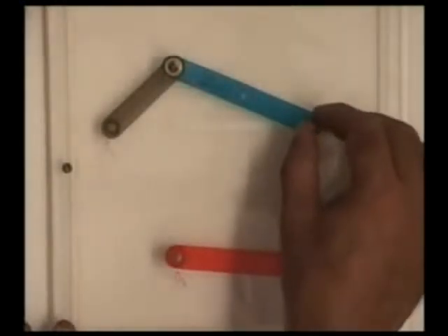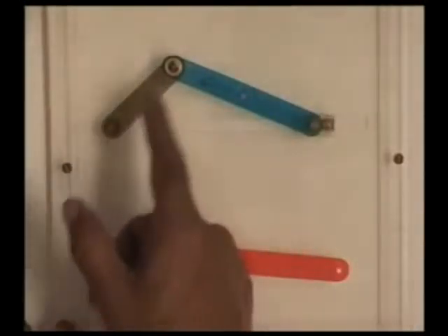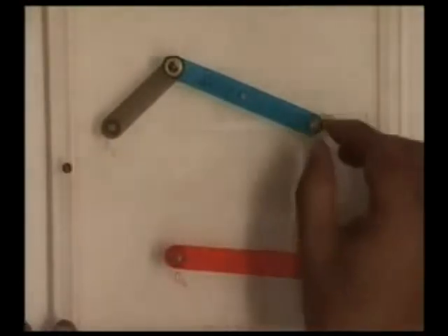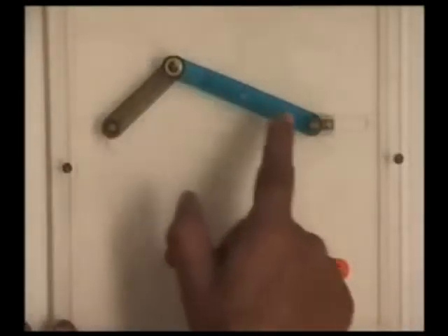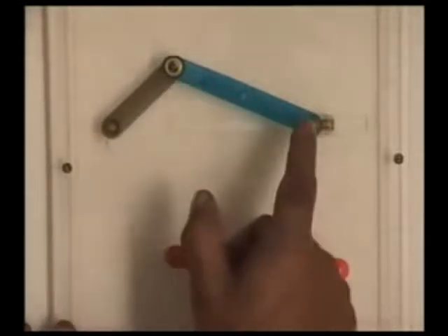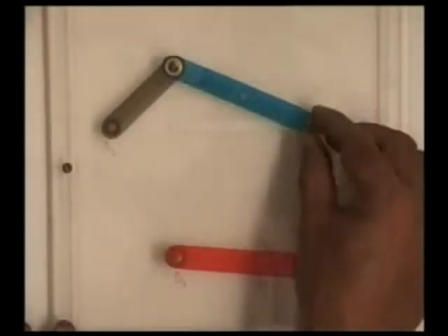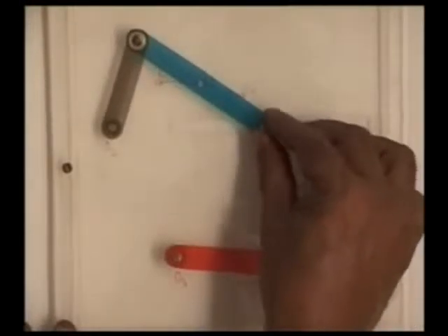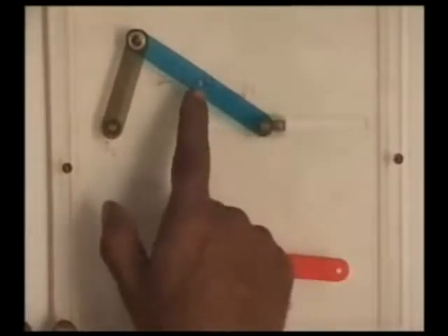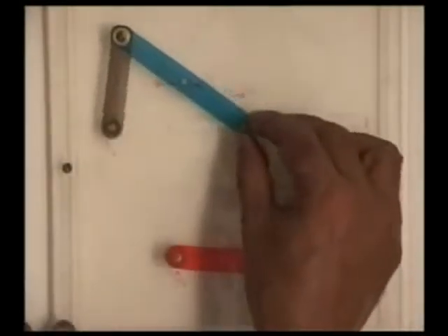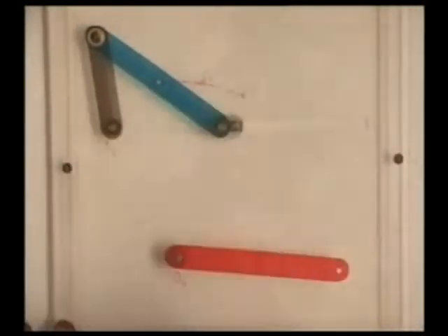After designing the slider crank mechanism as a function generator for two pairs of coordinated movements, we talk of the midpoint of this connecting rod. At the third configuration, say it is here. At the second configuration, the same coupler point, the same midpoint of the connecting rod, is here, and in the first configuration, it is here.